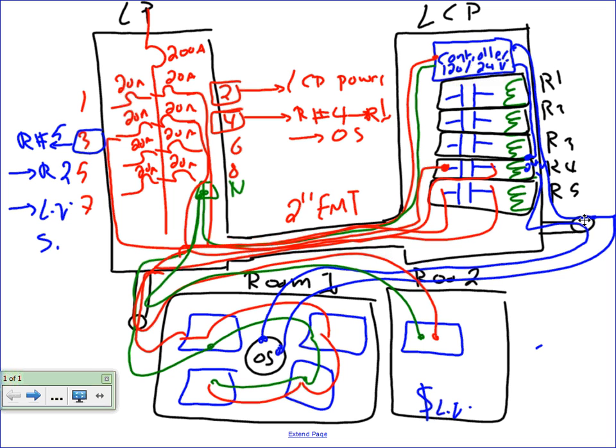The control circuit, let me do, again, blue for the control circuit. The same way, guys, the low voltage switch is going to have 2 wires coming out of it, at least. I'm going to land one wire on this side. The other wire, for the most part, goes to the controller. And from the controller, I'm coming back into the relay. Now, these can be coupled together, and I'm just making a symbol here.